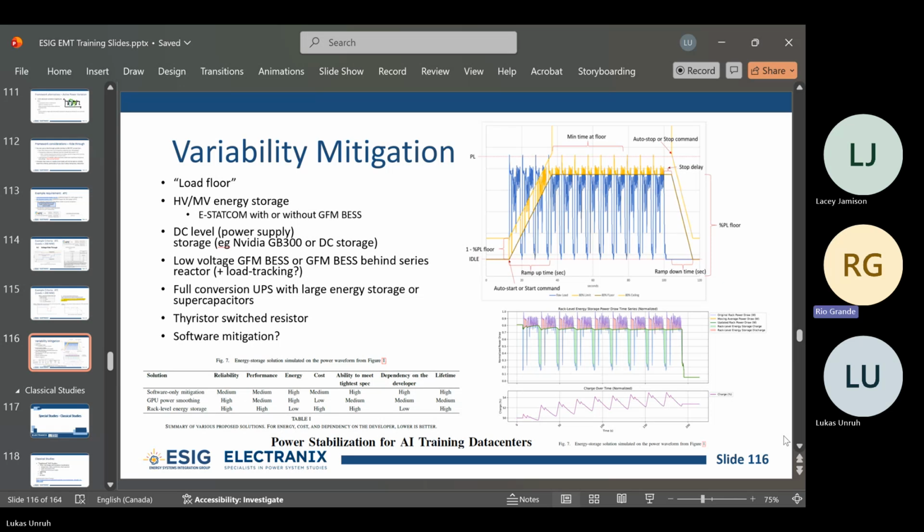Because the difference that a 1,000 megawatt data center coming offline makes in the impact is very different than a smaller load. That's true, but if one 10 megawatt load is the same as a 100 megawatt load, then in the aggregate those smaller plants still have an effect. So you should hold them all to the same minimum ride through and then let them maximize from there. That was kind of the same justification FERC used when they said you have to register converter based resources below the regular NERC threshold, because they make a difference in the aggregate.